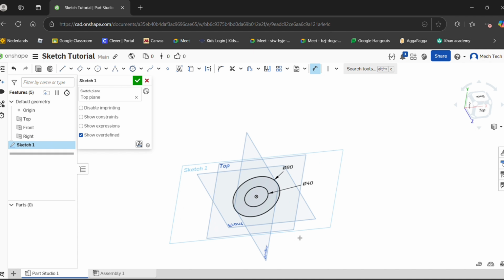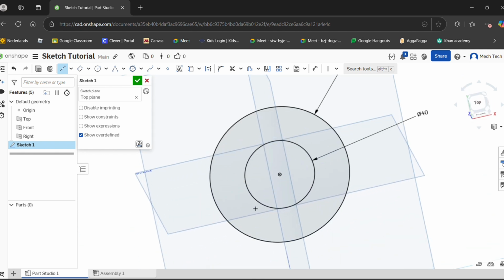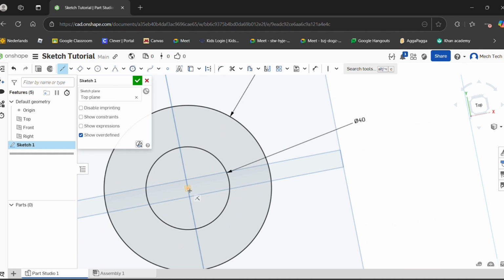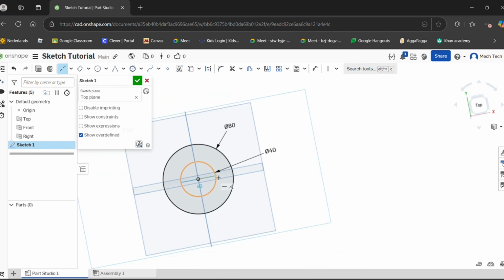So now that those 2 are defined, we want to make the rod of the key. One way we could do that is you could use the midpoint line. As shown in this video, we know that the midpoint of the line will be the first selected one, and we can select that as the origin. You could say we want it to go out to the edge of our first circle. That fully defines the line.